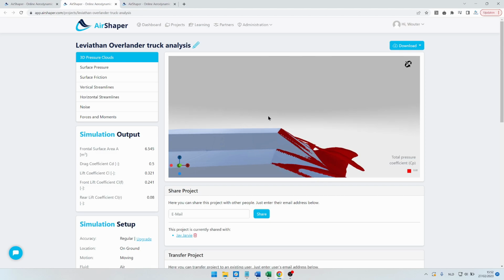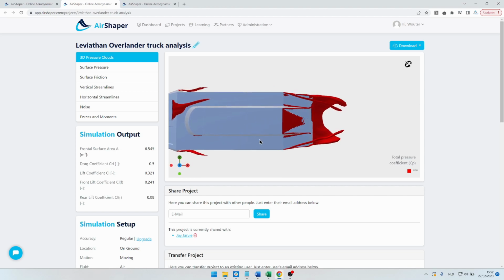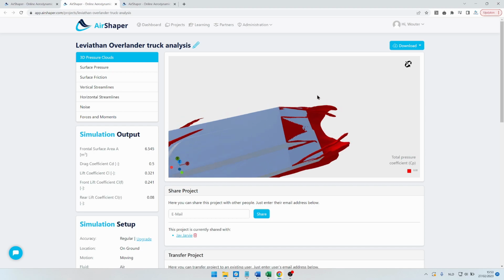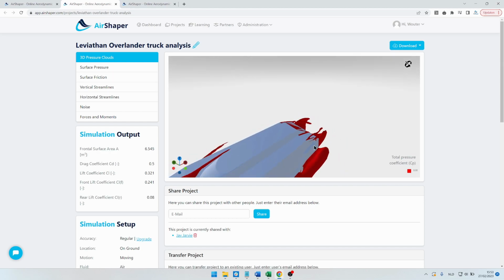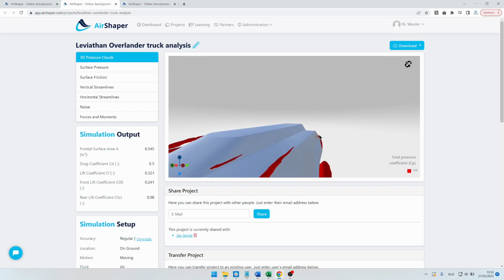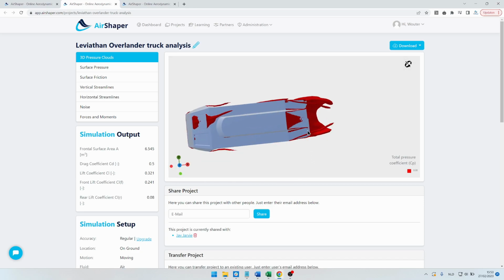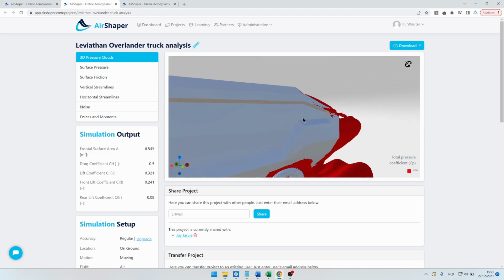You get some flow separation here. The flow tries to reattach, and also in the horizontal plane, the air is trying to curve via the sides into this low pressure vacuum almost. It's not a real vacuum, but a low pressure area left behind the central tunnel. And again, as the air curves around this edge, trying to make its way inward, you get again a vortex there and flow separation. Same for the overall air, trying to curve around the edge of the truck to join the air at the more central area behind this truck. So again, strong vortices which usually indicate loss of energy.